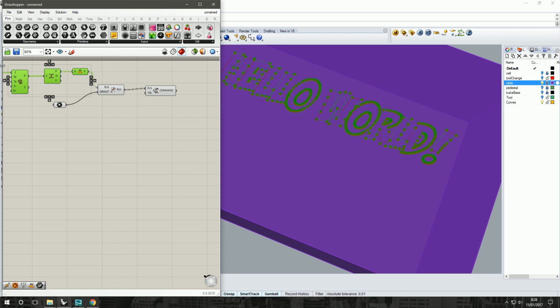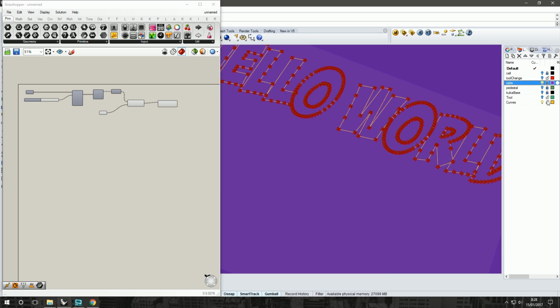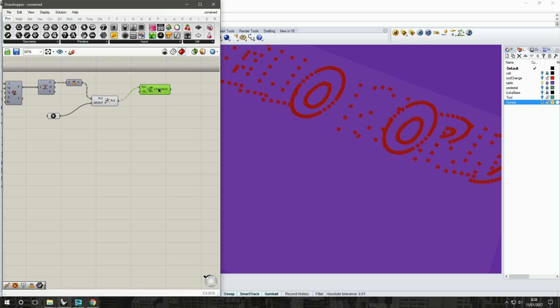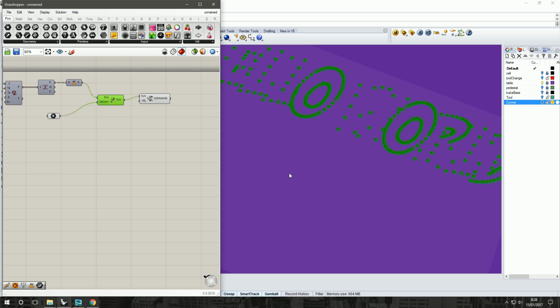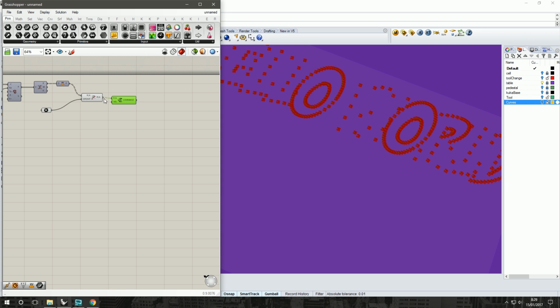We'll hide all of this now. I think we don't need to see that. Just middle wheel click and turn off disable preview. We can get rid of our curves as well. And there's our plane, so we can see that we've orientated them towards it. The ones that are further away sort of tilt, which you might not want to use if you're doing something like calligraphy. You'll have your angle set and you want your pen to be angled the entire time. So we've got our linear movement.